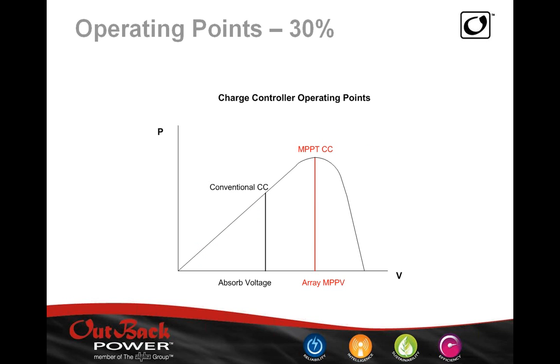What that does is it will harvest more from the PV array than a conventional charge controller, and it's thrown around that the gain is roughly 30%, which basically means more charging current for the batteries. That's the advantage: you are able to charge your batteries, thereby prolonging the life of your batteries, and of course the available energy that the batteries can give you.